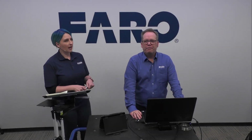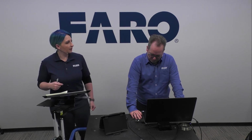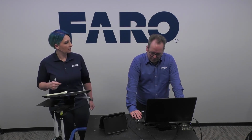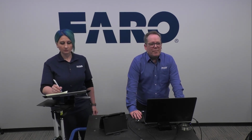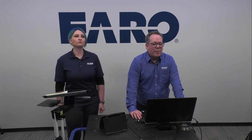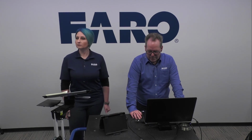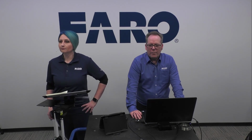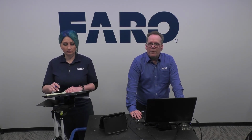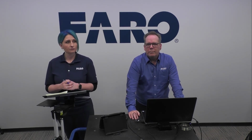Brian wants to know if we can export point cloud data in like a PDF or something that's a little bit easier for people to look at. You know what? I'm going to defer to Derek White on this. Derek, I know that there's a lot of options, right? What do you want as the deliverable is a question that you need to answer, but how would you address that, Derek? Well, certainly one deliverable would be that in the 3D image, you can take snapshots at any viewpoint and export those in your report, or print them or export them to a PDF.